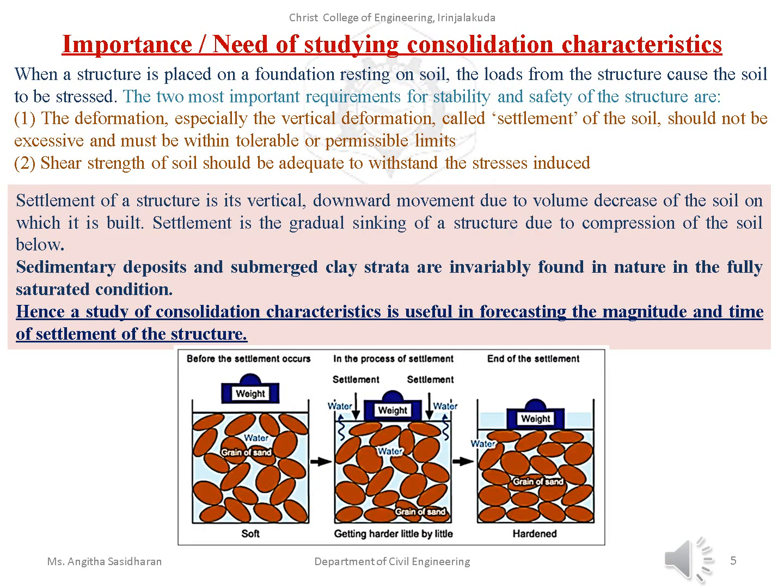What is the need or importance of studying the consolidation properties of soil? For a civil engineer, why is this consolidation of soil so important? If you're considering a structure that has a foundation resting on soil, the load from the structure is transferred to the soil, and the soil is again getting stressed.